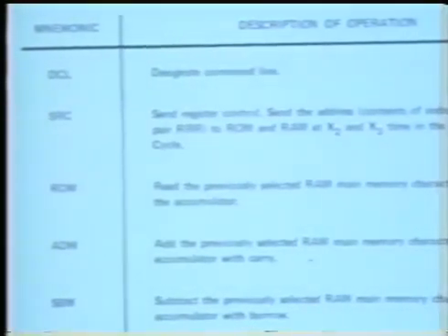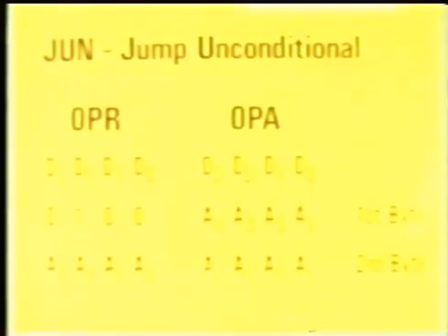I/O and RAM group instructions allow you to send data back and forth between the CPU and RAM and to get data in and out of the system. Let's look at a typical instruction, the 2-byte jump unconditional. It's stored in successive words in ROM.